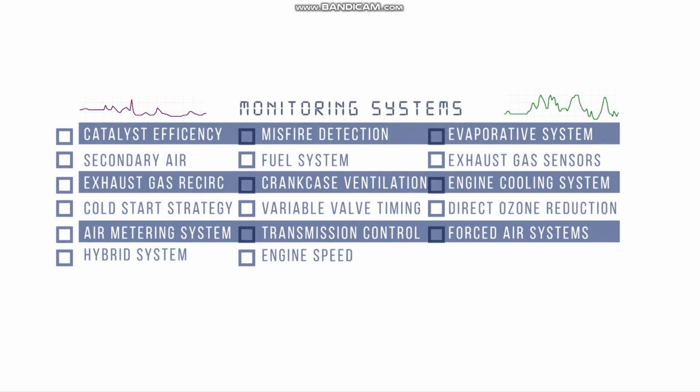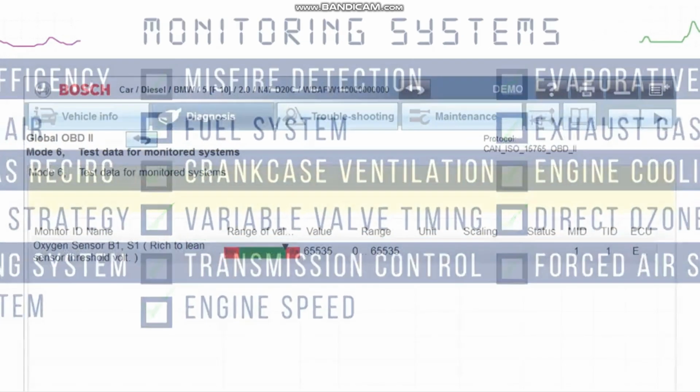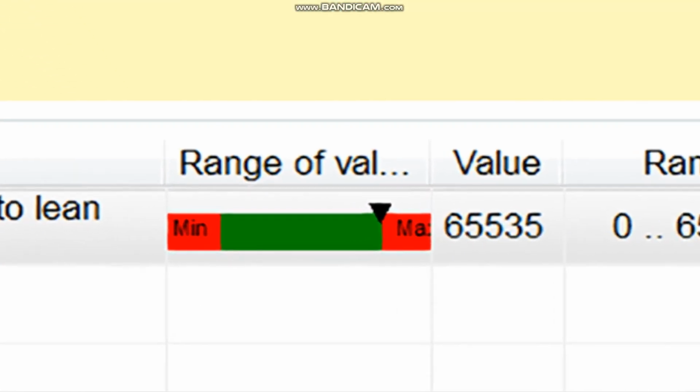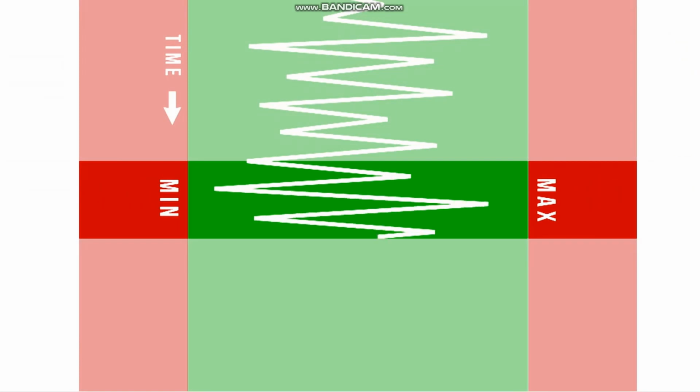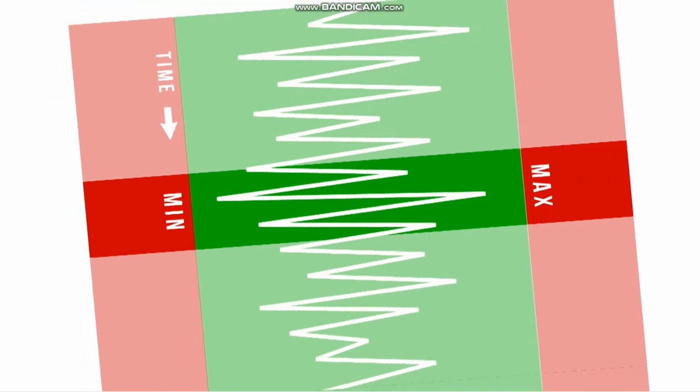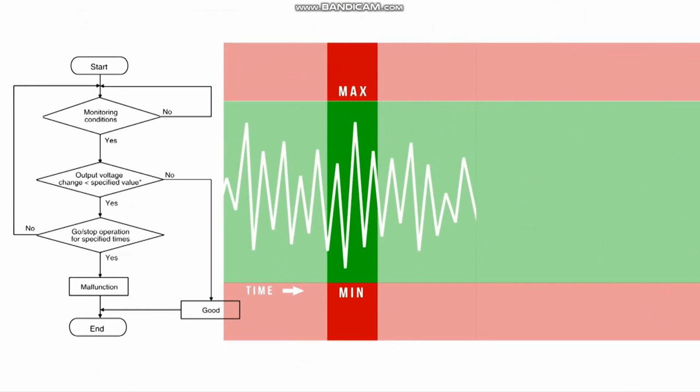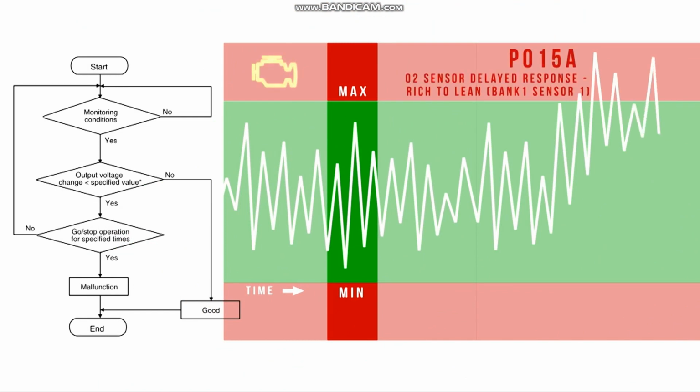As part of the OBD2 standards, OEMs must design their engine management systems to perform defined checks, monitors and evaluations to determine the operation of various emission components and to ensure that the vehicle emissions remain within prescribed limits. The different checks and evaluations carried out are referred to as monitors. These have a specific criteria which must be met before they run. Should a monitor fail, then a fault code, pending or confirmed, may be logged, depending on the severity of the fault and how likely it is to cause component damage or cause the emissions to increase beyond their limits.